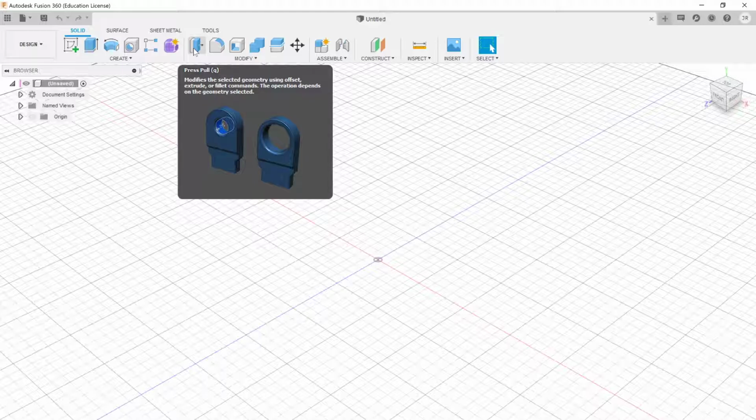So far what we've seen is extrusions, but the extrusions are usually only for going straight up, and that's kind of a limitation. So perpendicular from the sketch, we go straight up, and that's kind of okay, but we can't do really much with that. If we want to curve, or maybe want to make a pipe that bends, or a handle, then that's not so easy to do with just a plain extrusion. So Loft and Sweep are going to be powerful tools that we're going to use.